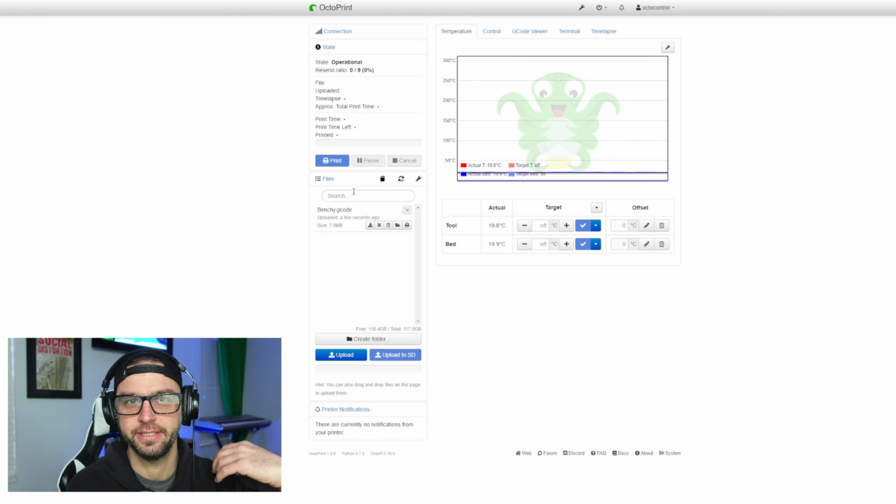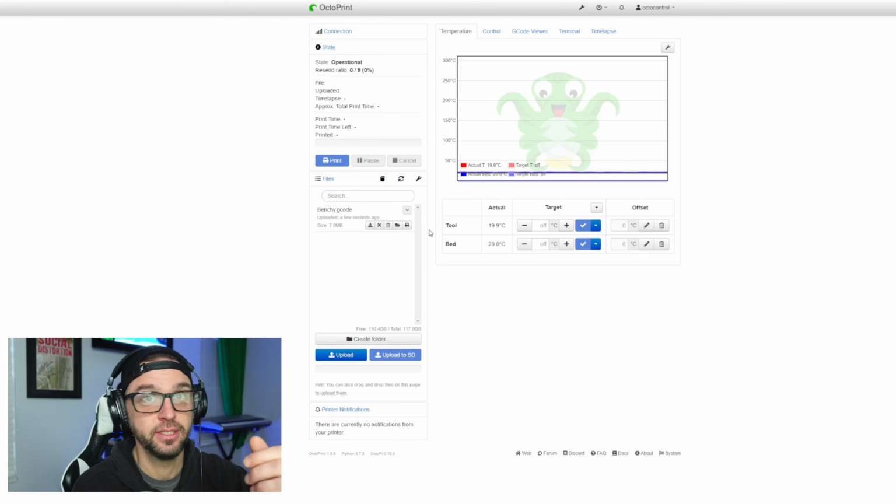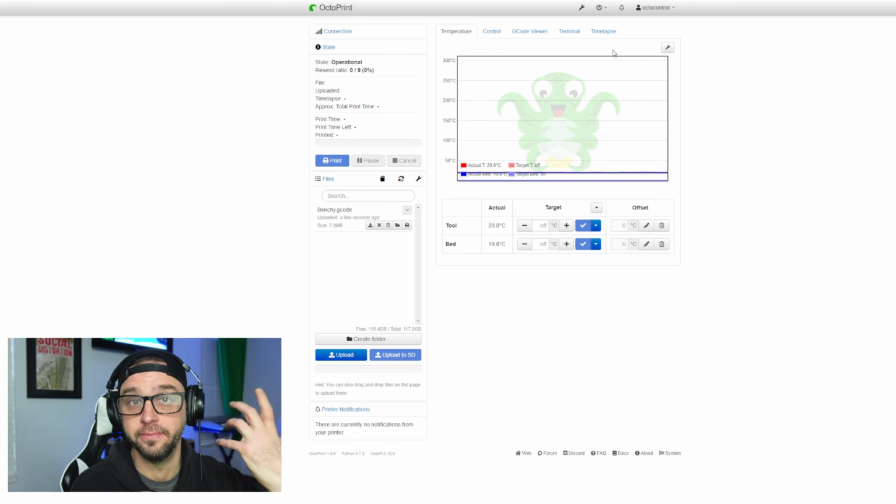It's very important as you have a 3D printer, you don't just start printing and think everything's good; get everything dialed in. So there's a Benchy. Now, if I wanted to, I could easily hit this print button here, and whatever settings I've defined in my slicing program like Cura, it will take that code, the G-code, and when I click print, it'll send it to the printer. Pretty simple.